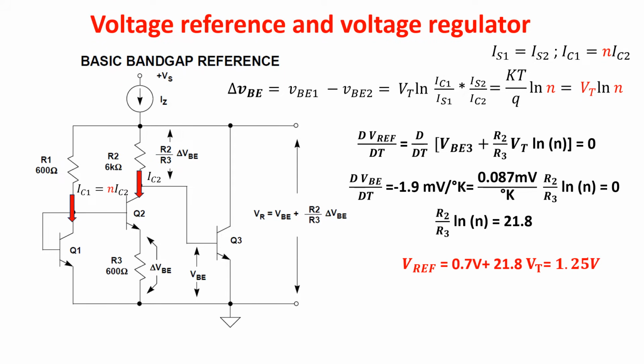However, the basic design suffers from load and current drive sensitivity, plus the fact that the output needs accurate scaling to more useful levels, i.e. 2.5 volts or 5 volts. The bandgap reference technique is attractive in IC designs because of its relative simplicity and the avoidance of Zeners and their noise.